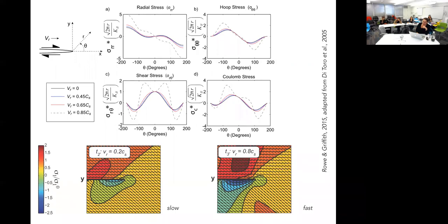And there's a fault propagating into it from Y into the center of the box. And the stress anomaly caused by slip on the fault is colored. So the greater the stress anomaly, the darker the colors get. And for red, it's going to be compressional. And for blue, it's tensile stress. So if you had an elastic blob or a fault breaking into it, this is how much stress or elastic strain you would get in your rubber rock, whatever it is, your elastic rock.